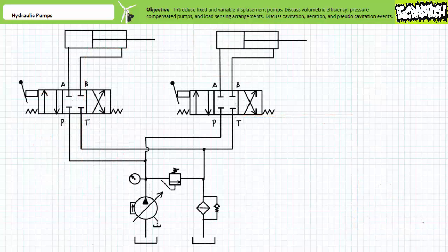Another application befitting a pressure-compensated variable displacement pump is that of our earlier example of directional control valves and actuators in parallel with one another that must be actuated independently from one another. When both directional control valves are in the closed center position, pressure quickly rises to the compensator setting and the pump de-strokes to 0 gallons per minute, thereby saving the pressure relief valve the responsibility of relieving pressure. Pressure is at the compensator setting and flow is static. The system is in high pressure standby mode.